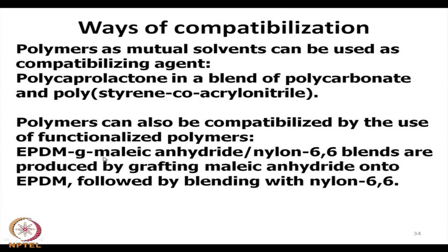When maleic anhydride is grafted on EPDM, that can be easily blended with nylon 6,6 polymer, and this happens due to the grafting of maleic anhydride on EPDM. Otherwise, EPDM is a hydrocarbon polymer and nylon 6,6 is a polar polymer, so they are not supposed to be miscible with each other.